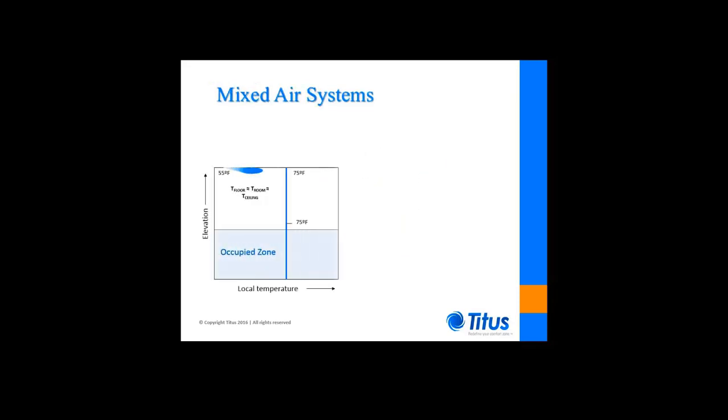This figure relates the temperature relationships for a fully mixed system. Note that there is little or no difference between the floor and ceiling level, and that both temperatures are very nearly the same as that at the control level of the space. As such, the airflow required to provide sensible cooling to that space can be calculated by this equation.